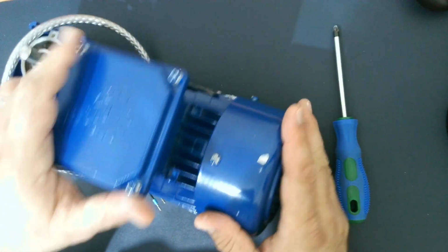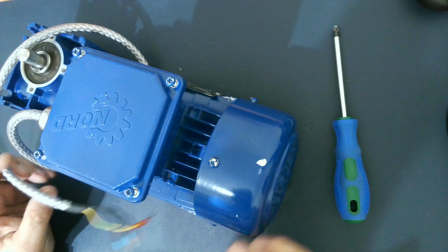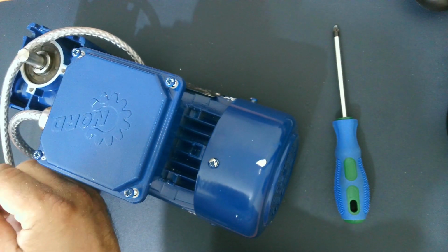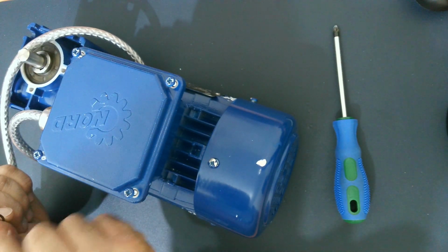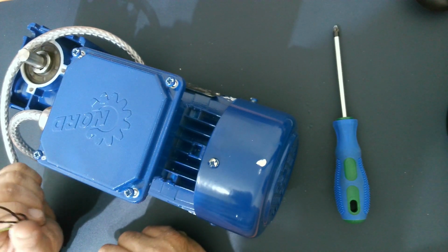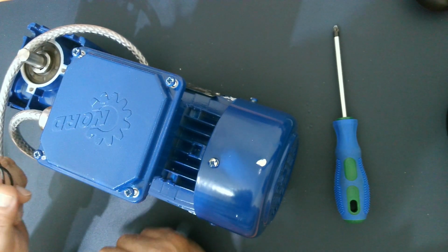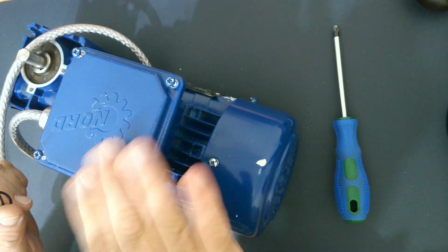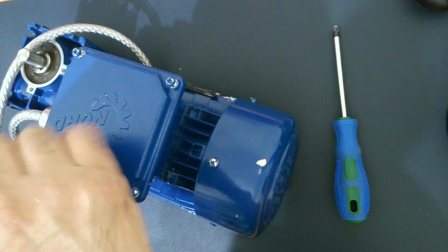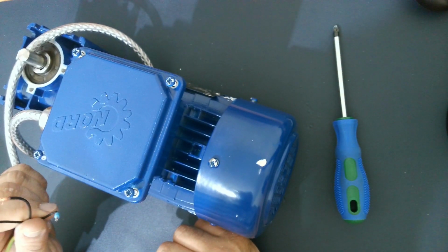So the question now, how do you know that this machine is a 3-phase? So I look for the terminals, but that one is not clear enough because I have here only 3 terminals, and I expect for this machine to have 6 terminals. We have 4. That one is the ground for the body. So we have phase A, phase B, phase C. So that one is a 3-phase machine.